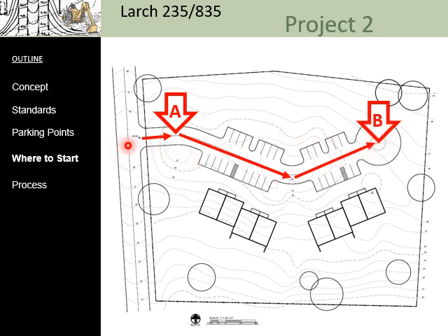So you can work your way from the entry point to point A. You can then go up this slope to a high point that's going to exist here that you will determine, and then down this slope to elevation at point B, which we have determined for you. Now, many of you are going to wonder, well, what is the appropriate elevation for this midpoint? And that's something for you to determine.